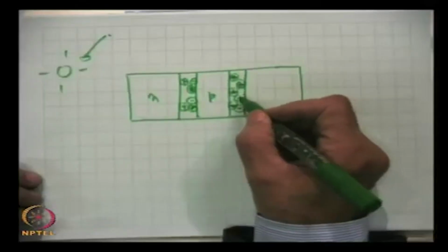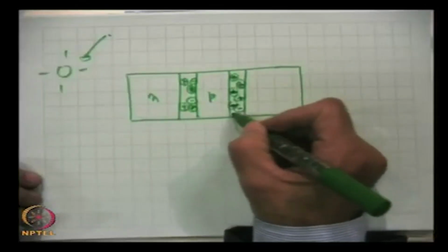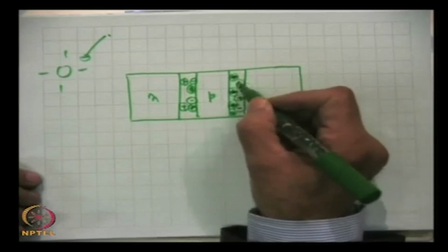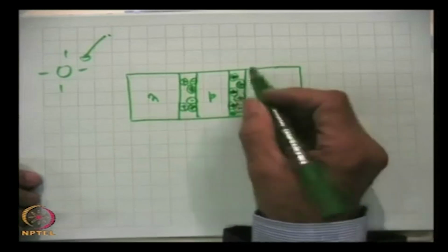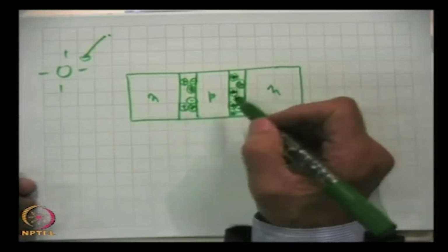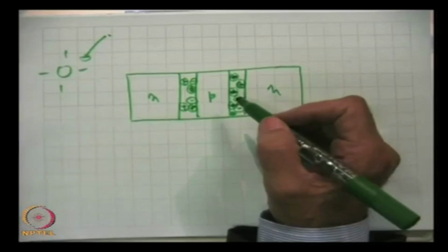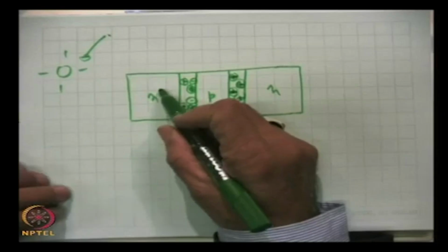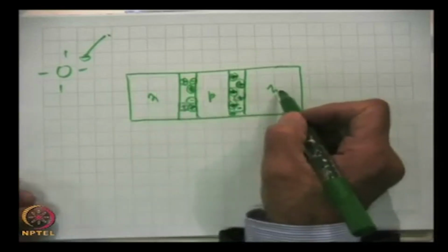So, they are rigid and they do not move, but because they are ions, there is a charge associated with them. The negative ions on the p side and the positive ions on the n side form the electrostatic charge which gives rise to the contact potential, which in the two cases may not be exactly the same, because the doping of this region and this region are different.